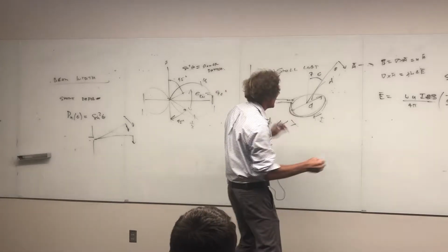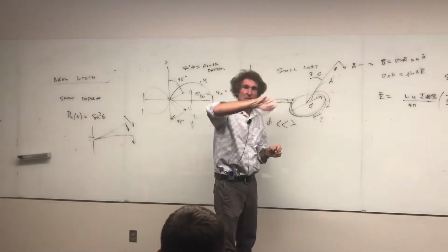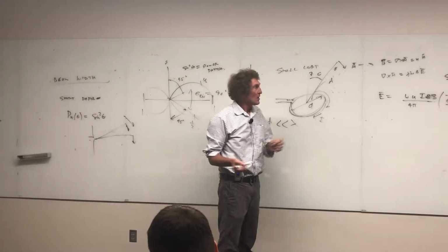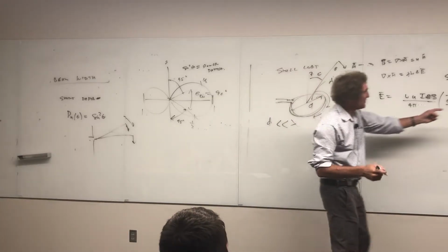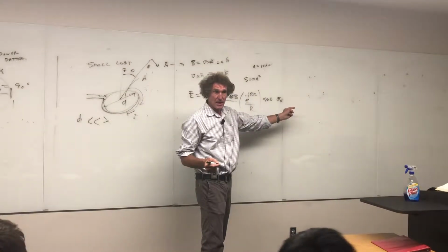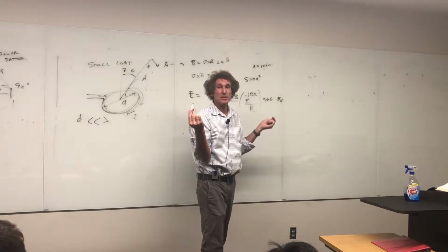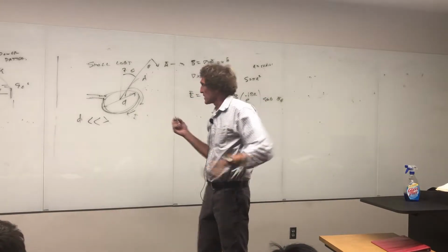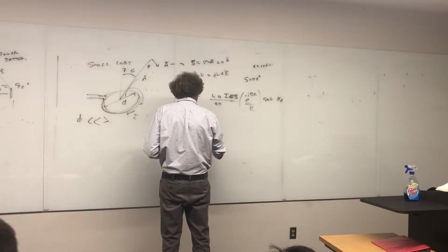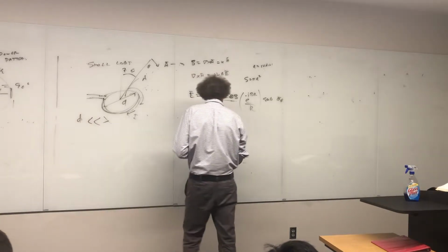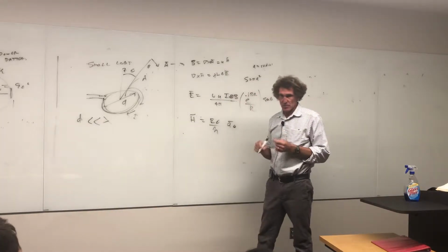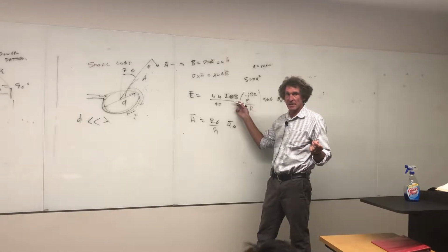For this particular thing, since the current is swirling, it's literally in the phi direction, isn't it? The current would be in the a phi direction. Do you agree with that, if that's in the xy plane? Well, the E field is too. That means the E field here is in the phi direction. It's not in the z direction. It's not perpendicular, or a theta. Follow me? And you can see how that basically is in the same direction the current is, or it has a projection in that direction. Now that's the E field. If we want the H field, we simply take the E field in the phi direction and divide it by eta, and then we put it in the theta direction. And that's what he has in his book there. He simply takes this value and divides it by eta.